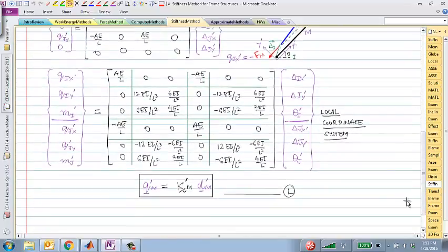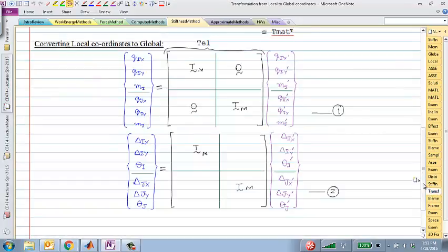And this is the other good thing about the stiffness method. Once you get all the steps down, that there's a local stiffness matrix, then you transform it, then you assemble it, then you solve it, with the boundary conditions, free and specified degrees of freedom. This procedure works exactly the same for trusses, for beams, for frames, for any structure really. And so a quick word about transformation.